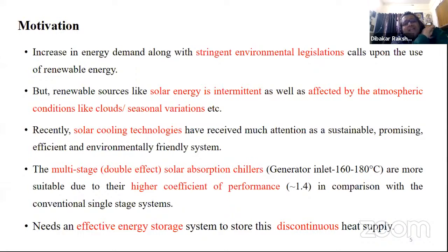Now, I think you will understand what is conventional and non-conventional type of cooling technologies. The cooling technologies which are not utilizing any active power for compression of the fluid. For example, in vapor compression, we require some sort of mechanical compressor. So if we don't require that, then it is known as non-conventional type of cooling technology. Of course, there are other non-conventional cooling technologies also, but the one which I want to highlight here is the vapor absorption type of cooling technology.